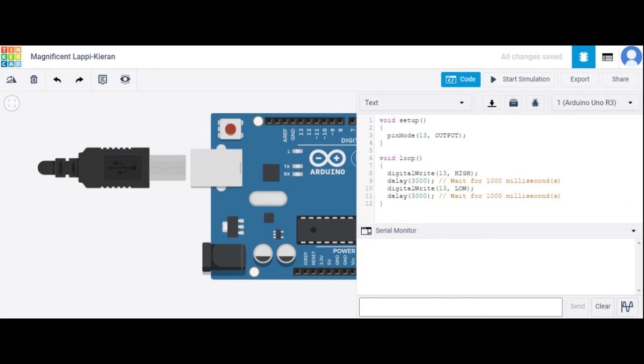See, another important point: if you want to send our program from your laptop or personal computer to the Arduino, we use the USB connection of the Arduino. It also allows us to send characters from our program to the PC. I repeat, in addition to sending our program from PC to Arduino, the USB connection allows us to send characters from our program to the PC to be displayed in a special console. So this is very useful to track bugs.